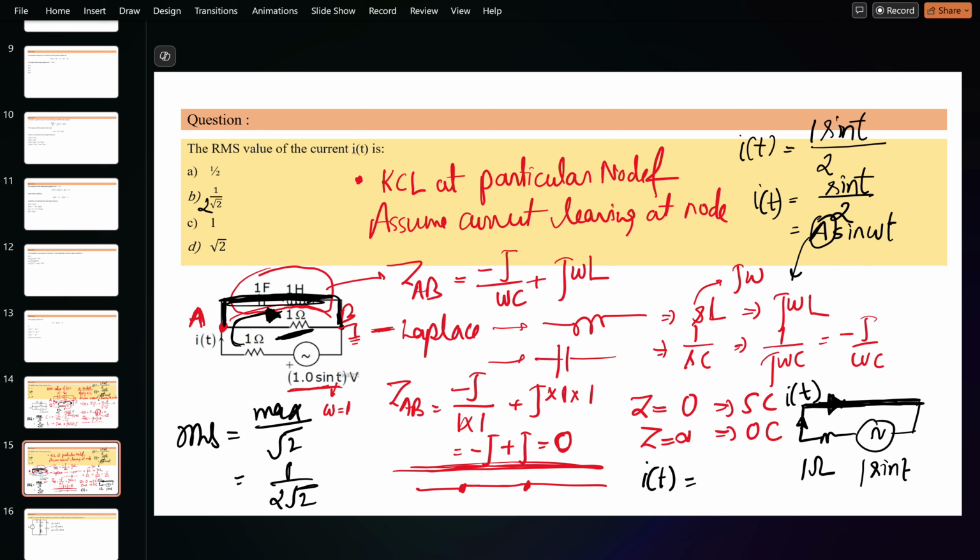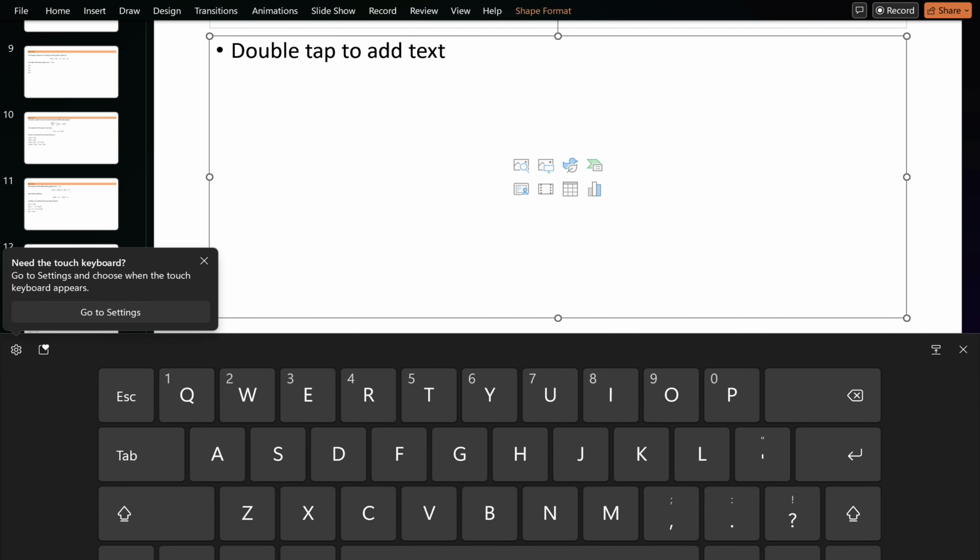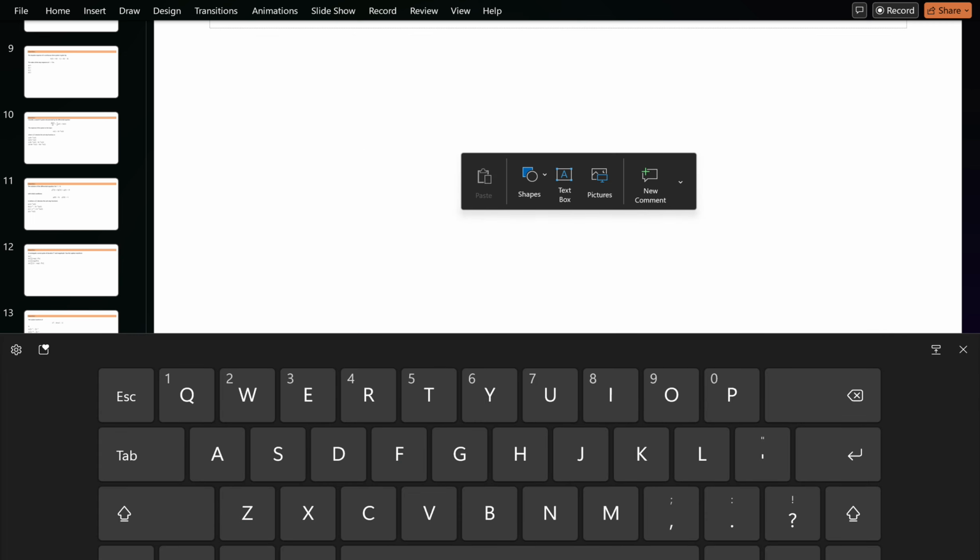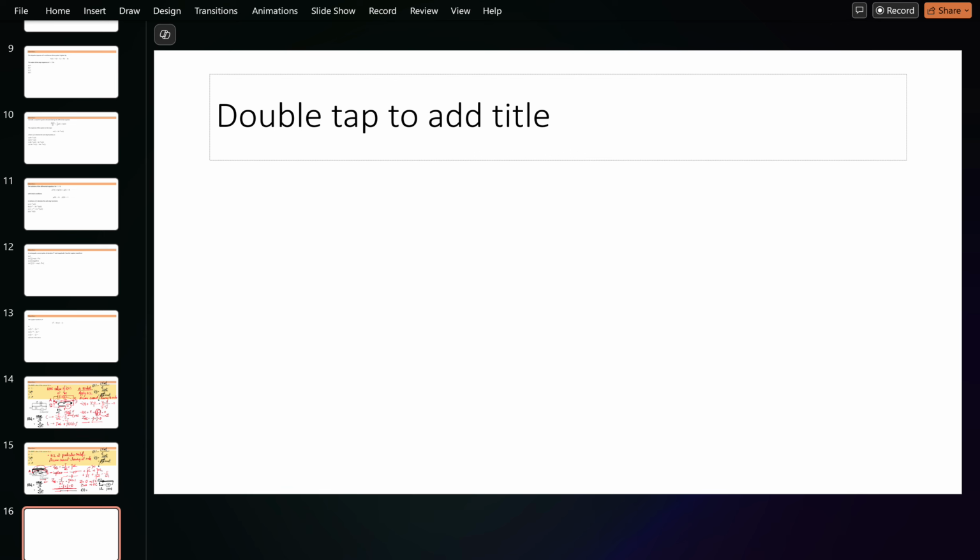Yeah. How is Z zero, sir? Z is 0 because if you see the impedances, two impedances were there. So let me take another slide for this. Explain that. So if you see the impedances, it was like this. There was one inductor and one capacitor, which was connected at a node, and here the terminal I have grounded.